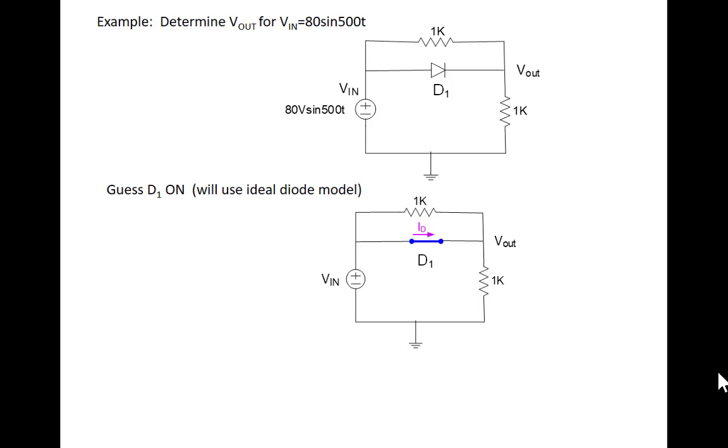So here's the circuit, and I want to obtain V out. Oh, the solution is easy in this case. A lot of times it is. What's the solution? What's V out? V in. Output appears across the input. It doesn't depend on these resistor values. So V out equals V in. Solution's easy.